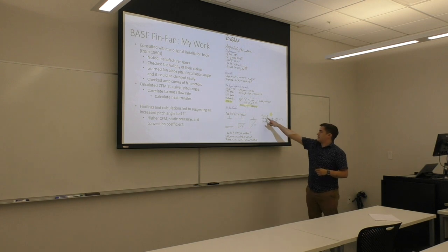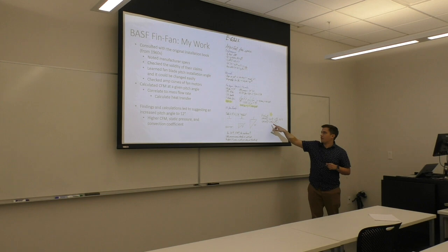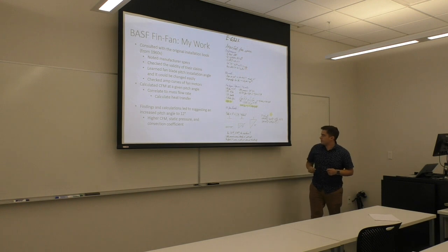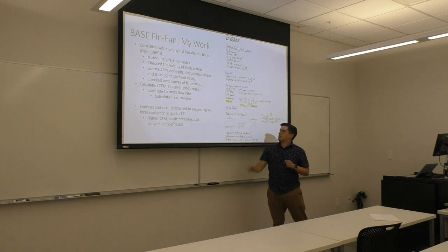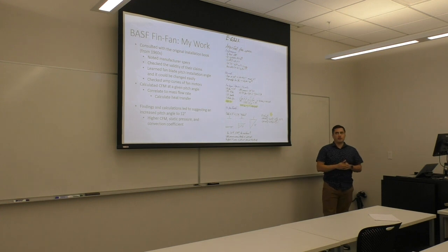So using some basic equations that we've seen a couple times today, I was actually able to confirm with the data given that the original heat transfer was supposed to be about 2 million BTUs per hour. I also had to do a lot of work to figure out what the original pitch installed was, which was 10.2 degrees, and I did find out that you could change it to variable angles between 10 and 15 degrees,